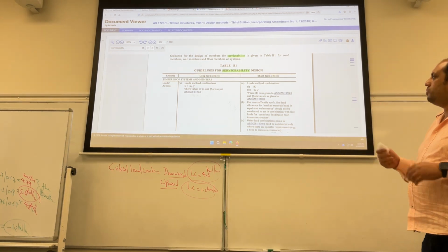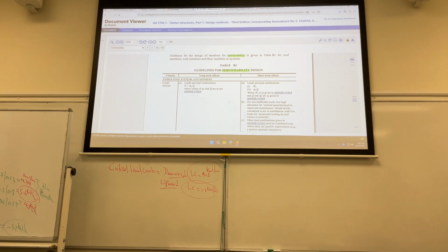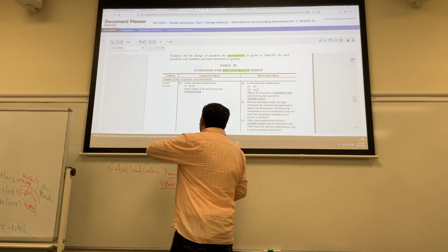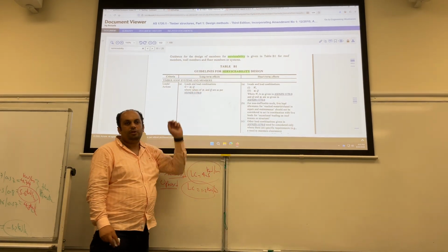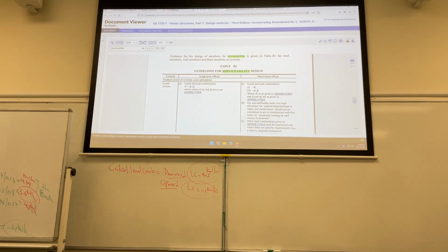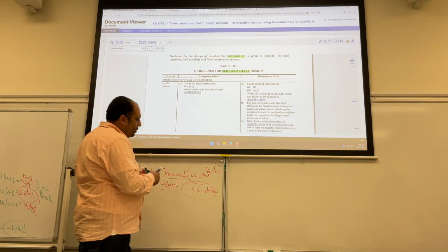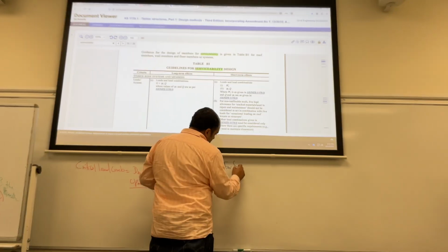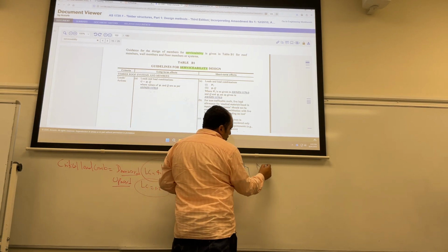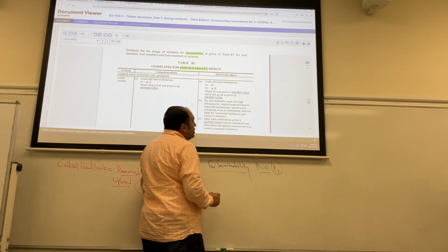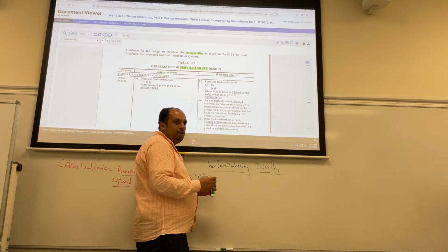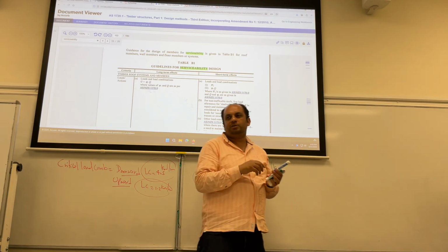So what is the load combination we need for the stability? Actually two. This one, G plus epsilon LQ. How much is G and how much is epsilon LQ? G is 2. So for stability, no K1. Okay? So we need just to go to table B1, and we'll calculate normally and compare which one is greater.